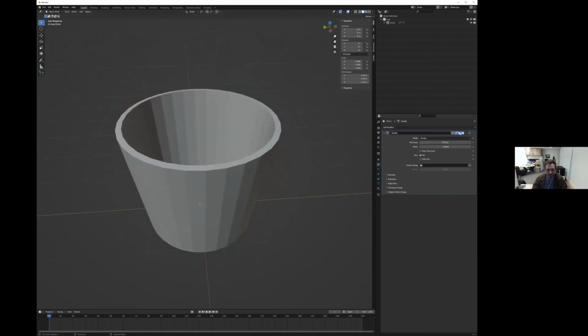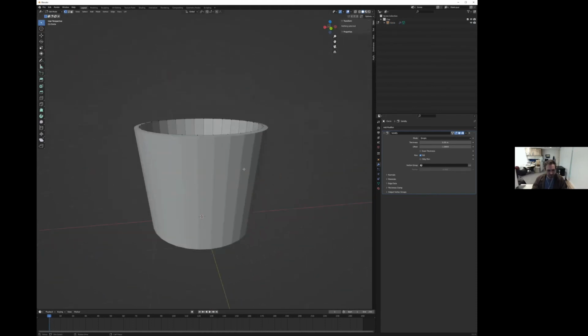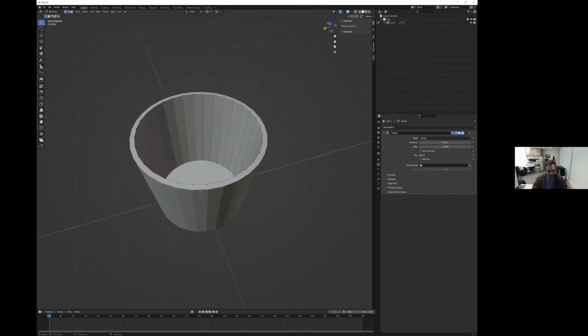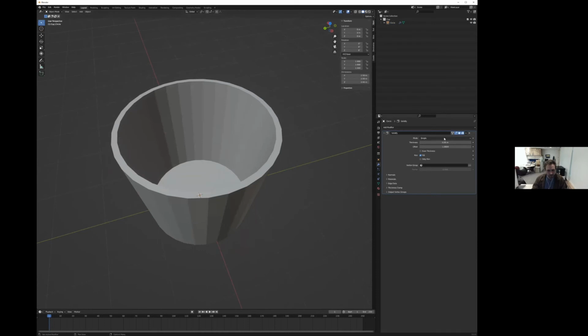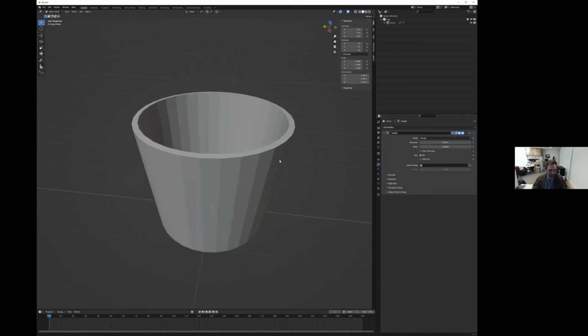And because it's non-destructive, I can turn this off and on, which is really, really nice. I can also look at the vertices. If I turn this on, you can still see this, but I'm not seeing it on the other side. Now, with this, we are actually going to solidify this, and we will apply this modifier because we do want to manipulate the mesh moving forward. We just wanted to solidify it so we can add some depth around the edge.